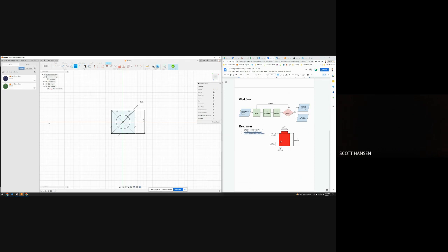And there's one more feature that I want to add from this layout sketch, which is going to be the thin wall. If I looked at it from the bottom, it's going to look hollow, and there's a thin wall that is 1 P unit thick. I'm going to add that using the offset tool, which will take some sketch curves and offset them a certain distance. For example, if I select my square, you'll see it creates an offset border. Let me drag that inside. And I'm going to set that thickness to negative 1.6. That's 1 P unit inside of that square. And you'll notice if we have that set up correctly, that should be tangent to the circle inside.